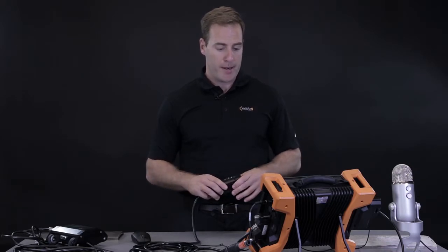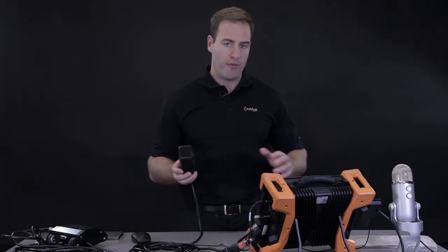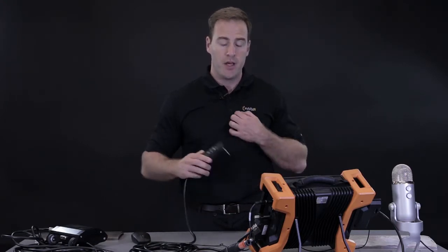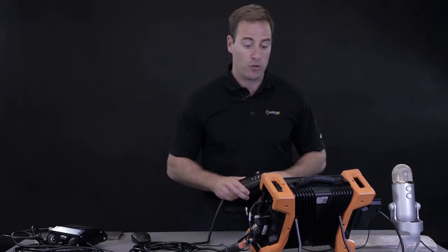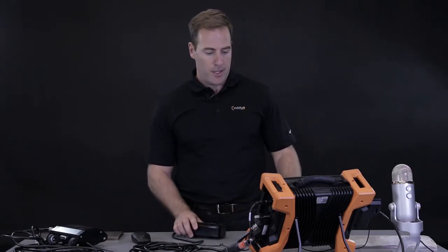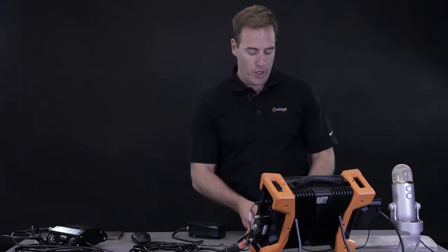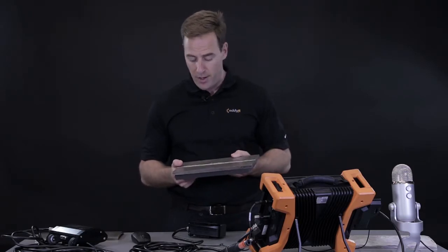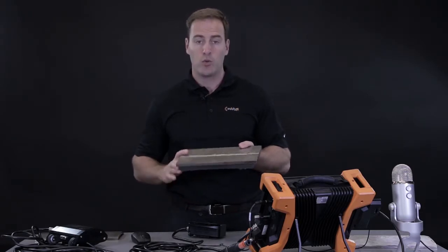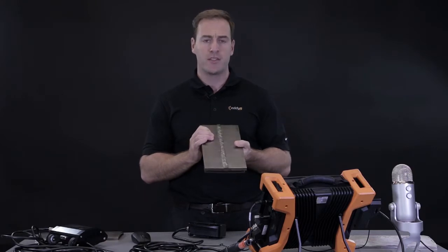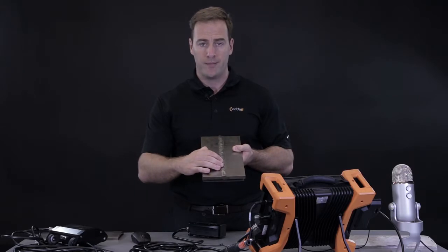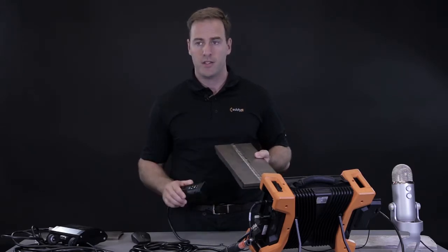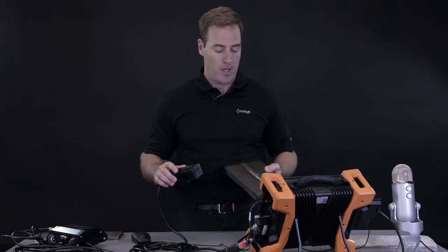Basically here, I've already loaded the setup file on the Reddy, and the probe has already been calibrated just to speed up. I just don't want to go too deep into the detail about how to use the probe. The sample that we're going to use for the demo here is a flat plate with a butt weld in it. There is some fatigue cracking which has been induced along the weld, and we're going to try to detect all these cracks with this butt weld here.